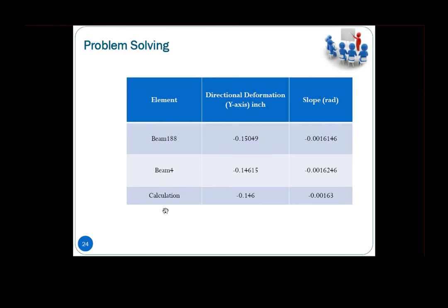Compared to what we are using here, the Euler-Bernoulli beam models. I've just now, I didn't really mention it. So this is the difference why we have calculations of 0.146, because in our Euler-Bernoulli beam models, we didn't consider that when it bends, you don't have the shear deformations due to this shear force. But the Timoshenko beam model basically considers these shear deformations due to this shear force